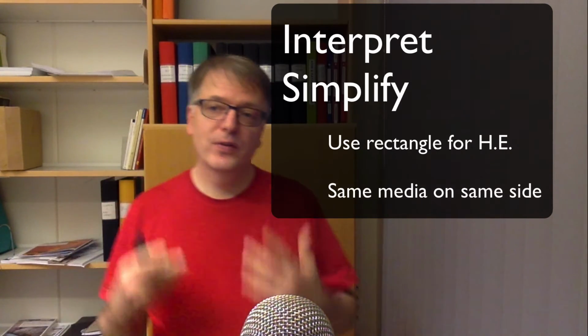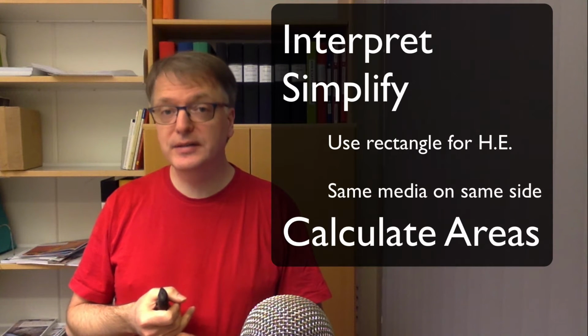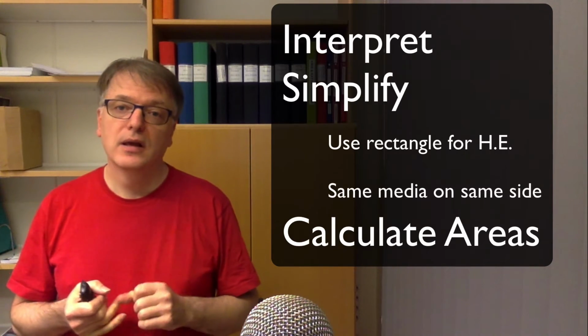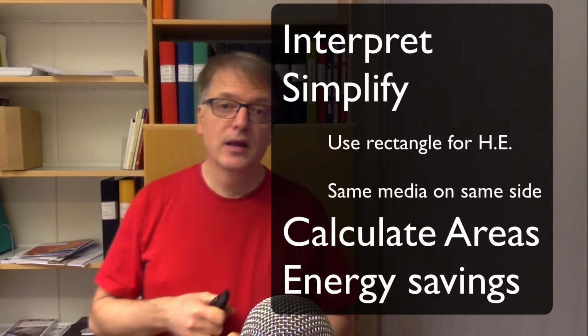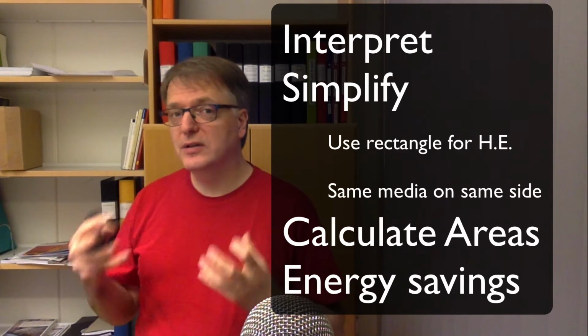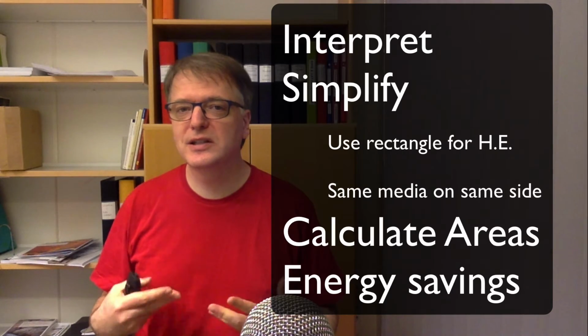Okay, once you have done this simplification, you should calculate heat exchanger areas, for the two heat exchangers that you should calculate the area for. And then when you've done that, you should identify and estimate energy reductions. So they have done some clever designs in this setup, and you should try to figure out approximately how much energy they have saved by choosing this clever design and using these heat exchangers in the manner that they do.